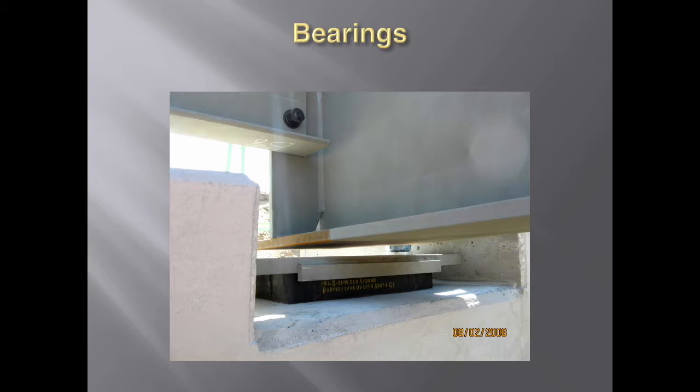And when we go out on the bridges themselves, everybody gets excited because we make sure the writing's facing towards the center. And of course, the guys out there don't understand why. But for us, it's a big thing. That way, if we have an issue, we can go back and look at the test results on the bearing itself and find out why it failed.